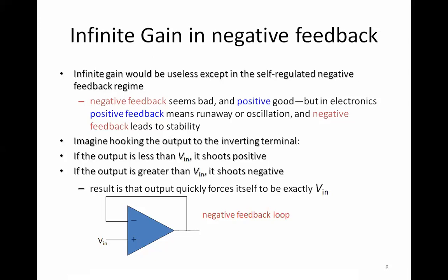So which means my positive feedback is going to be ruled out, right? I'm not going to use a positive feedback. So we are going to use the negative feedback. Negative feedback is going to be used. So why are we using that? Because it brings in something called stability. It can make your output as stable as possible, which means I am trying to nullify the oscillations as much as possible. I want to reduce these oscillations as much as possible.